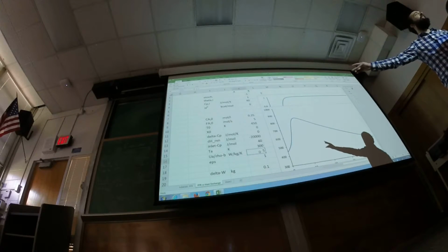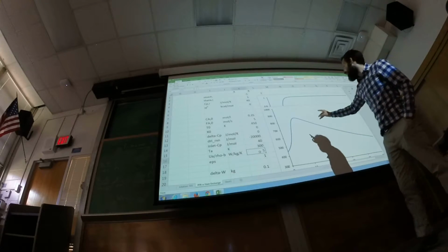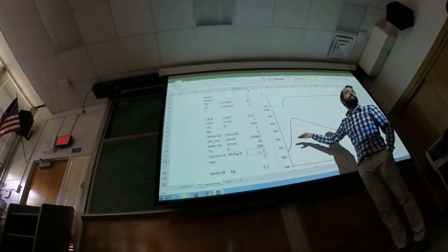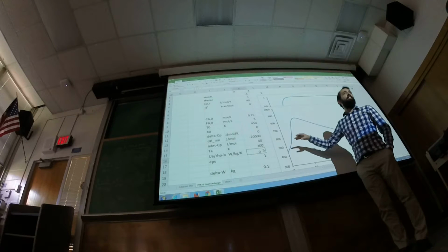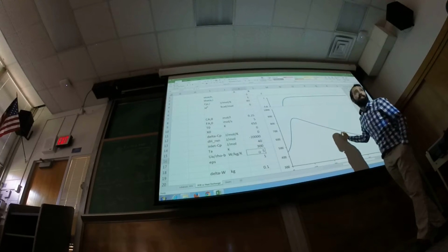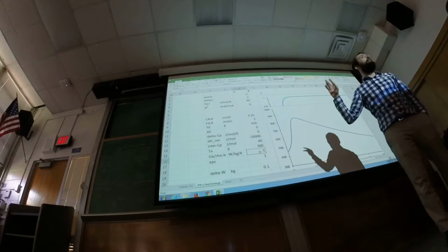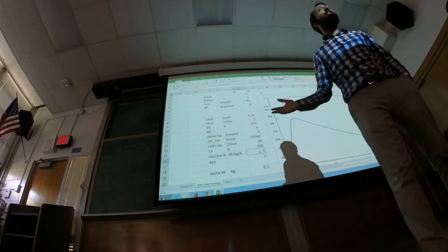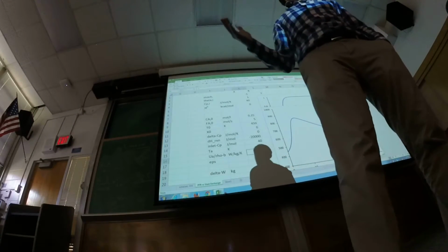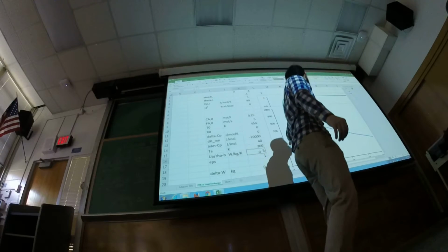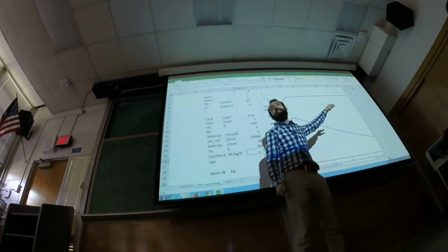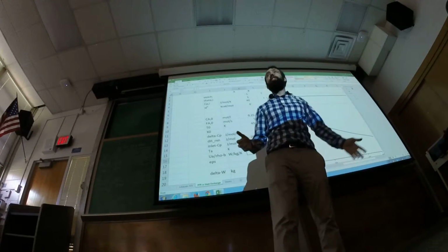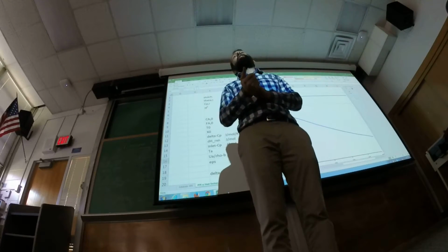So first, which curve are you talking about? The temperature curve. So the temperature curve is going to do what? It's never going to decrease. That's correct. If I set that to 0, I'm essentially running this adiabatically, right? That's the exact same as an adiabatic reaction. So this is going to go up, and it's going to be constant at some temperature corresponding to 100% conversion.